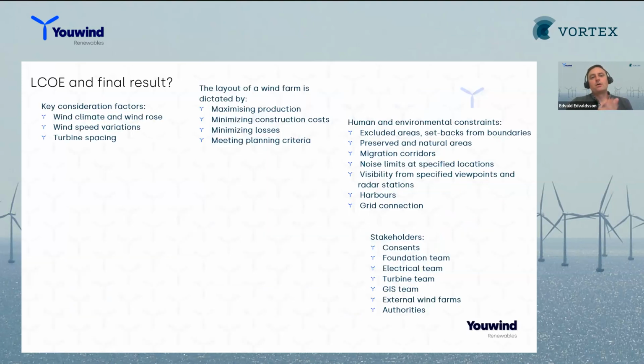So we're talking about LCOE, so levelized cost of energy. Levelized cost of energy is the lifetime cost of your energy project, essentially divided by how much electricity it has generated in the lifetime. So cost and electricity generation are the most important aspects, and therefore the wind speed is obviously very important, but also other losses such as wake losses, electrical losses, availabilities, and the overall upfront cost of the capex, and the opex, the operational cost, also plays a very important role when you're looking into offshore wind farm development.